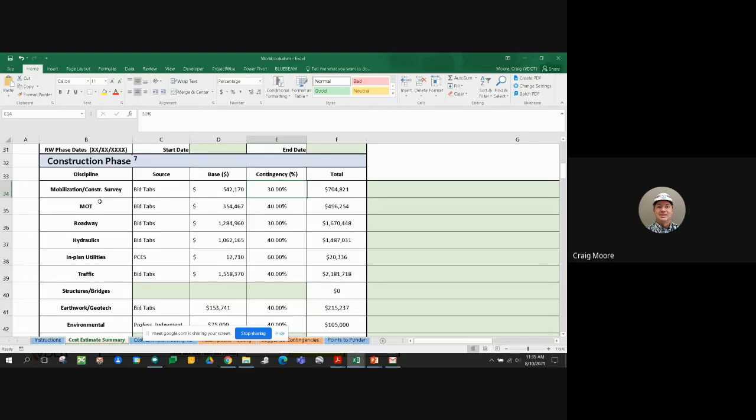Maintenance of traffic had items in our estimate for which we had worked on developing a maintenance of traffic cost estimate, but still realizing that there's a lot of uncertainty associated with that. This is an arterial out there, Route 220, a lot of traffic, the potential to have multiple setups, takedowns, and how this would end up being phased. We have a 40% contingency on our maintenance of traffic.